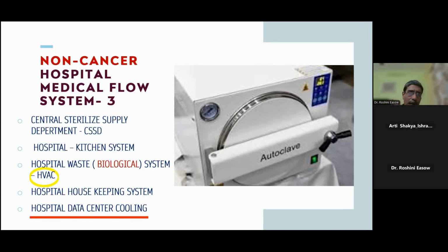Now this autoclave does two things. One, it cleans, and it sterilizes the products with hot water. Simultaneously, this room becomes heated because it generates a lot of heat. So we are working out that instead of giving the heat to the room, if there is any heat duct process, you can remove some of the heat outside.